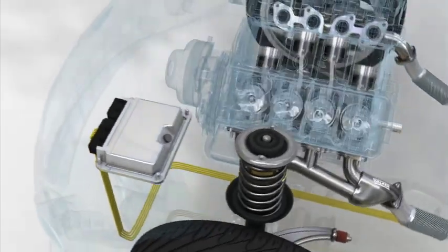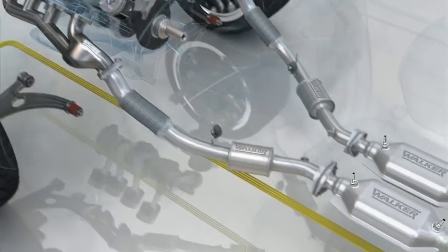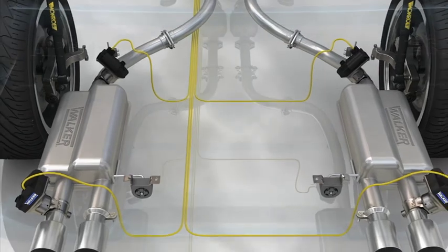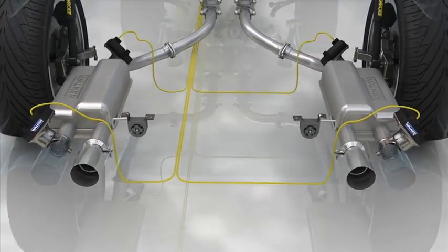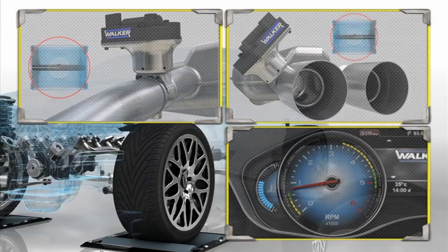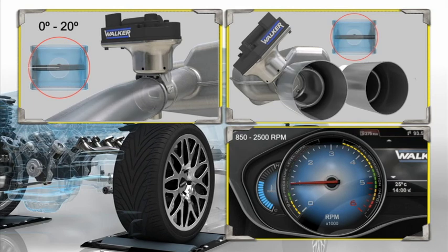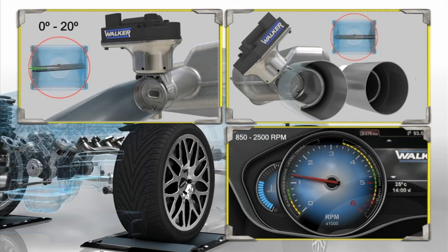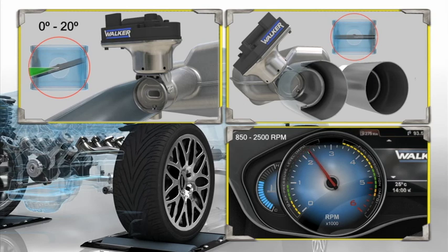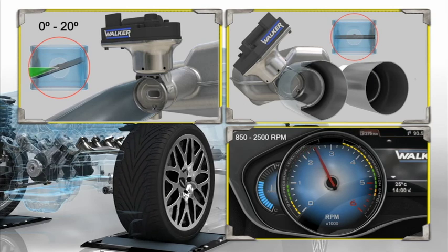The tailpipe valve is also controlled by the electronic control unit, ECU, of the vehicle. This, depending on the engine load condition, opens or closes the central disc to regulate the internal back pressure of the exhaust system, in addition to the noise level of the rear silencer. Its basic operation is simple. At low speed, 0 to 2500 RPM, the back pressure of the system is very low, so the TP valve remains completely closed, helping to increase the back pressure.